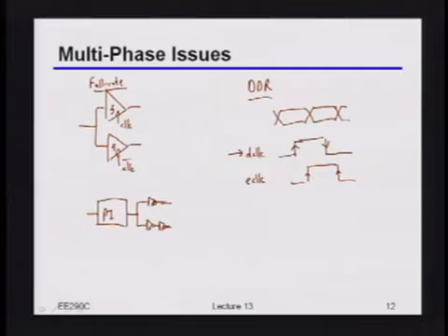And you just interpolate from the phase interpolator again? Interpolate from the phase interpolator. What exactly do you mean? What I mean is, can you use the same 4 phase inputs and generate the edge clock also? Okay, yeah, absolutely. So you could indeed, right? I've got 4 phase inputs into that phase interpolator, giving me 1 output. Well, I could indeed just copy the phase interpolator, take those same 4 phase inputs, but rotate the code by 90 degrees, right?